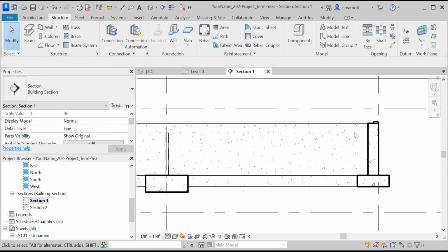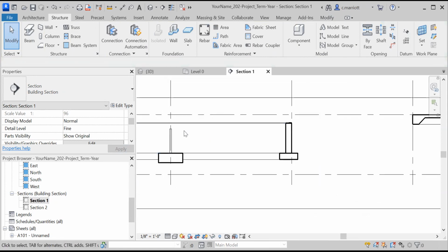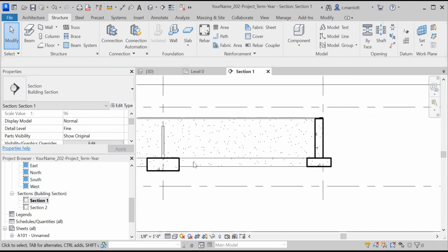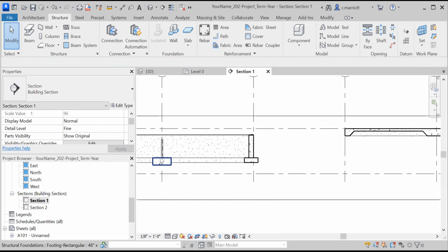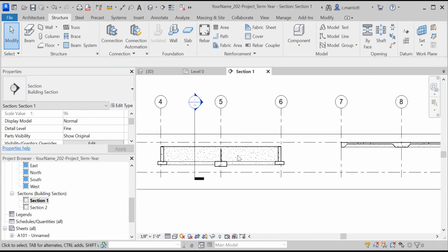After looking at the spanning parameters for that beam, a more efficient beam would be where it's not quite as long. This is a 20-foot span in this direction. So I'm actually going to move this column over, and I'm going to add a second one. So there'll be 2 columns supporting a beam that crosses here, and that beam will be broken into pieces, but basically they will stop over the columns.